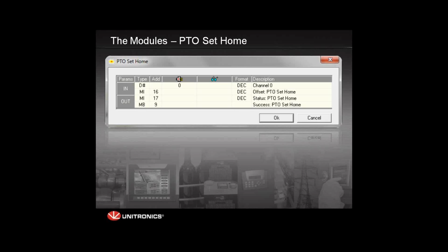If we're using a relative movement, when we set the point as home, we're telling the counter to count from 0. What it means is that if we set a target of 1000 and we set the home at the same time, the movement will reach 1000 pulses and will stop.